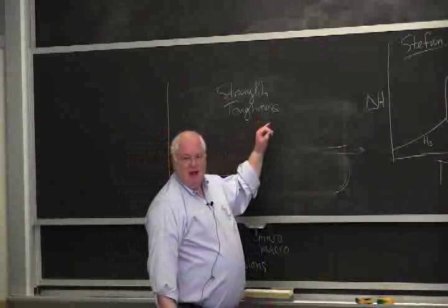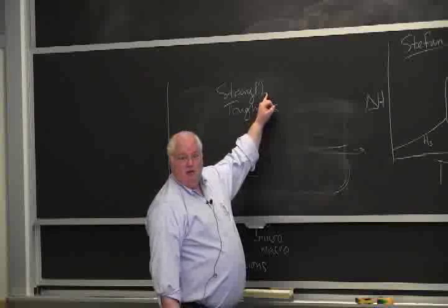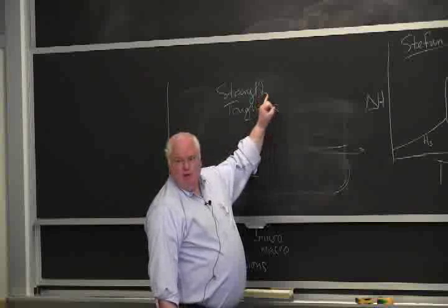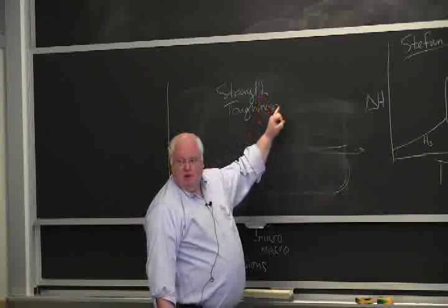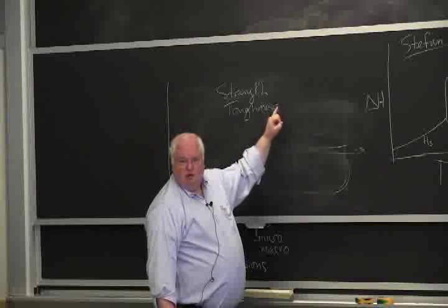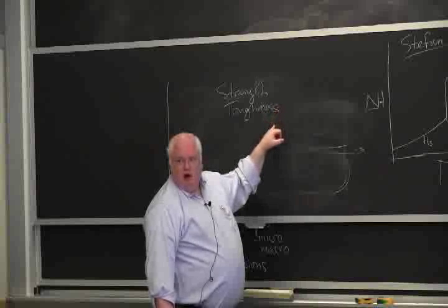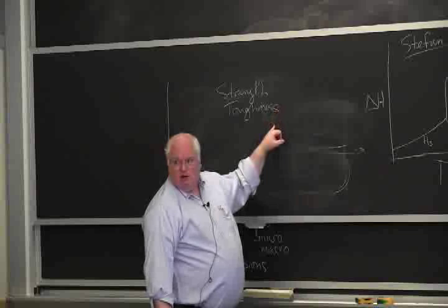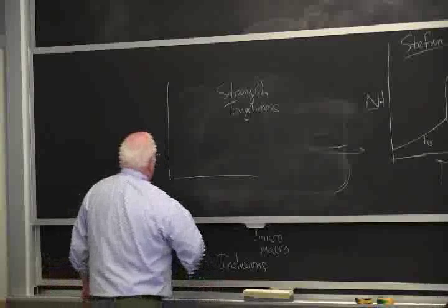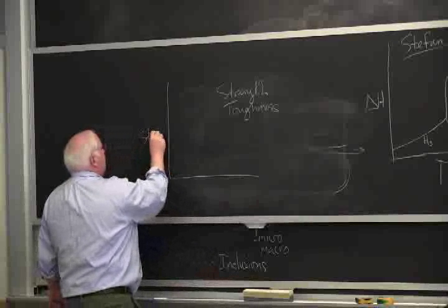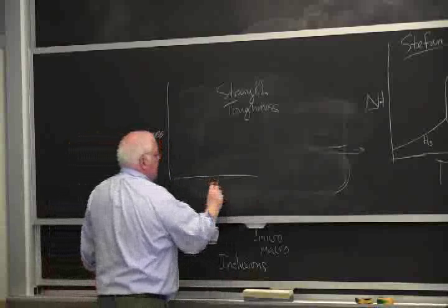Glass is actually fairly strong. It's actually stronger than steel. That's why fiberglass composites can be reasonable strength. The fibers are stronger than steel, but they're not very tough. They shatter, they're brittle, there's not a lot of energy. And in fact, what I can plot here is stress versus strain.